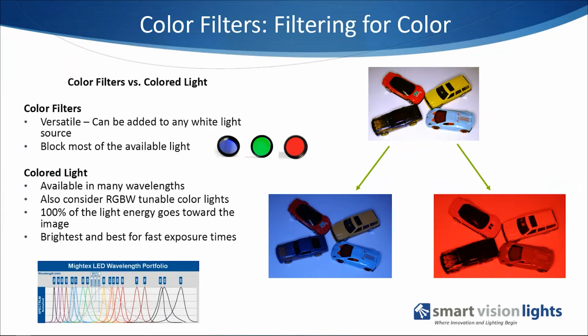So colored light always is an advantage over colored filters for getting the brightest and best performance of however much money you spend on the lighting. And when we're talking about fast inspections and exposure times, you're often spending quite a bit to get the brightest light, so you want to maximize that. Nothing wrong with using colored filters, but just think about it, and buying a colored light is often the better case and bang for the buck as far as tuning your system.